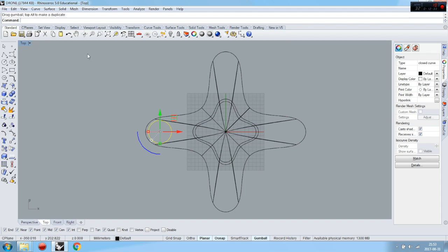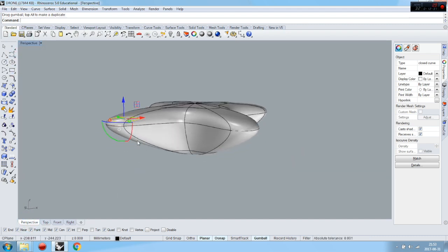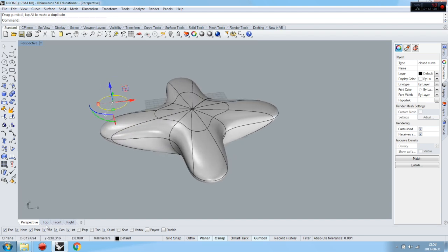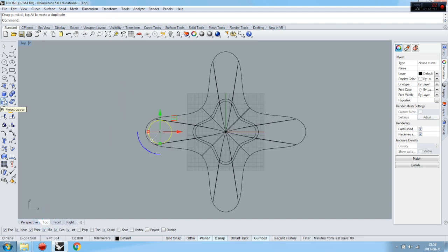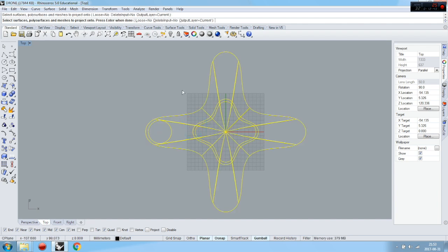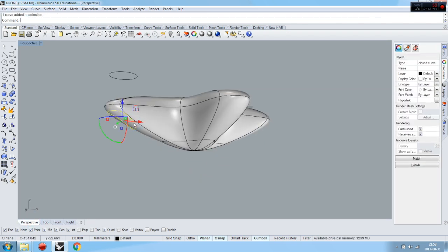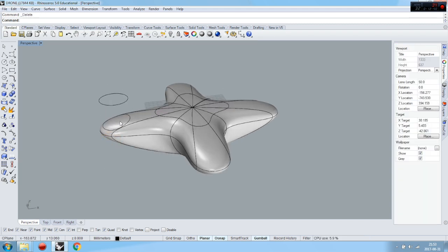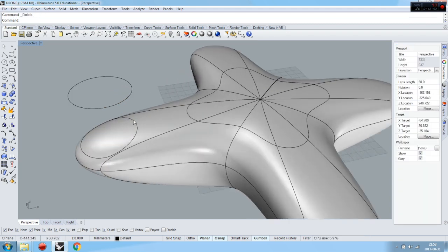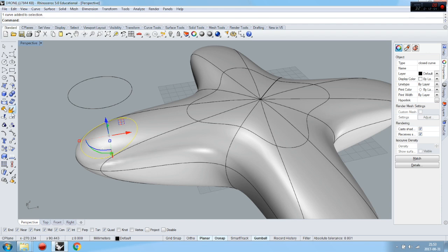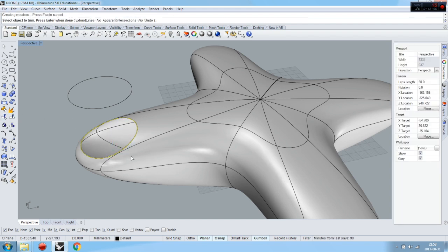I'm going to project first, because then I'm going to cut with what I've projected. Look, it's here. I'm going to View and Project Curves onto my objects, and then it's projected. I don't need that one, so just press delete, and you can easily trim it like that.